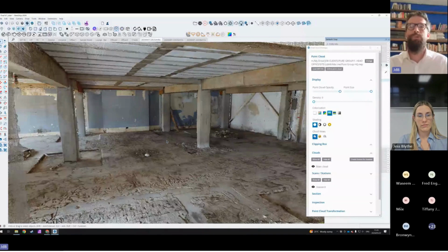So a good way to show this point cloud to a client is to ensure that they get a similar view of this point cloud as you would when using some VR goggles or when you would print this out on paper. So a great way to showcase this is under your view menu, to make sure that all the hidden geometry and additional features are turned off.